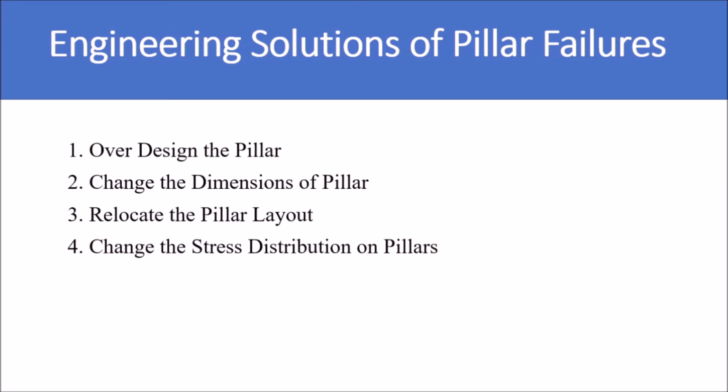To avoid pillar failure, we can over-design the pillar, we can also change the dimensions of the pillar, we can relocate the pillar layout, and we can change the stress distribution of the pillar.